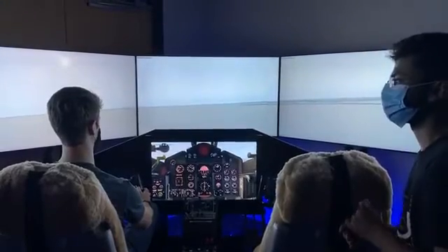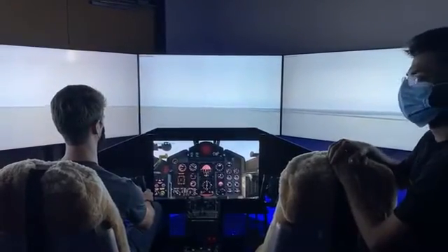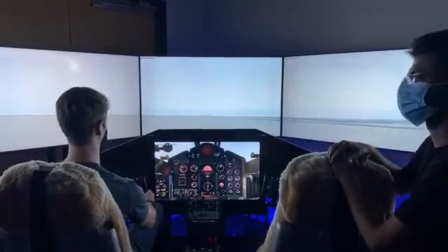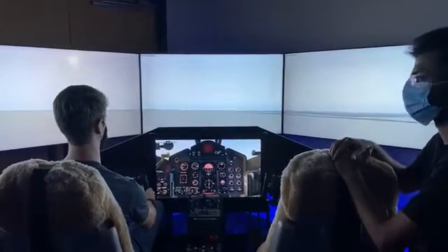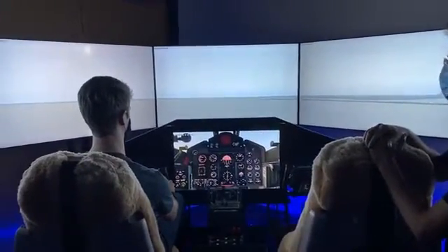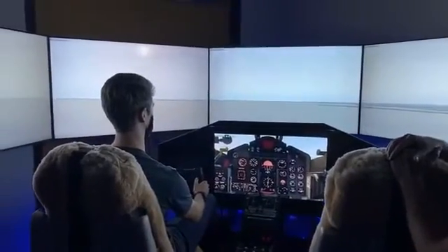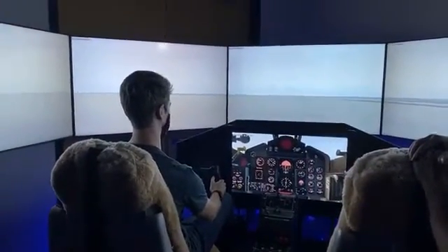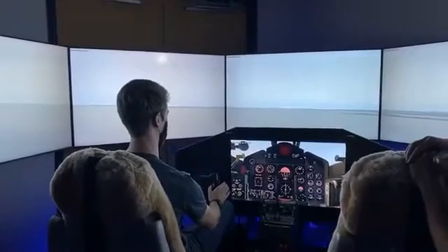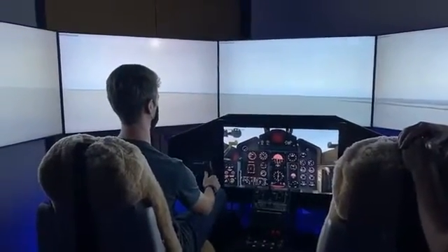So, when naval aviators are landing on an aircraft, the first thing they do as soon as the wheels hit the ground is they actually go back to full power, which seems counterintuitive since you're trying to stop in a short distance, but like Bob said, that's to make sure if you have a bolter, which is what they call it when you miss the cables like I just did, so you don't stall as soon as you go off the end of the runway and hit the water.